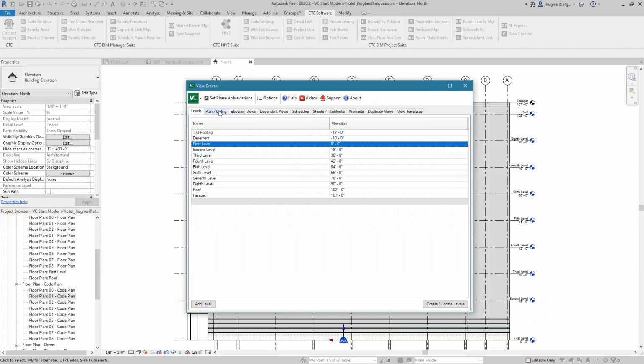A lot of you guys work on large projects where you need to split the project up by match lines. And that also is actually a more tedious project. Hopefully you guys are duplicating those as dependent views so that if you've got annotations that occur over the match line, it will maintain all of your annotations to be the same between each of those different views. So you don't get one dimension on one side of it, and then it reads differently on the other plan, which is what it would do if you did a one-time snapshot of it, or if you just didn't duplicate with anything. If you just duplicated the view itself, it may not have that dimension.